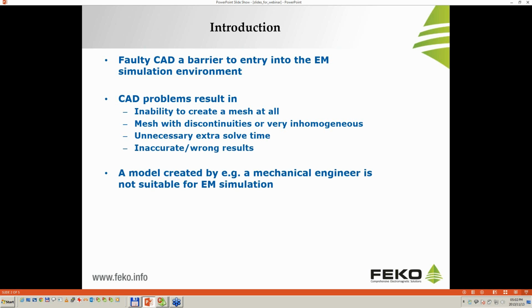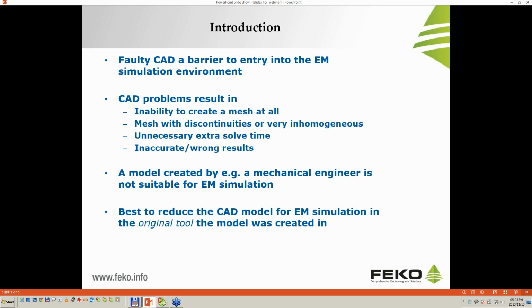Now, quite often a CAD model is created by a mechanical engineer and it is not suitable for EM simulation. For example, there will be much detail in the model. For example, there could be rivets and screws and many small details that we don't really need in EM simulation. Now, it's always best to reduce the CAD model for EM simulation in the original tool the model was created in. But that is not always possible, and many of our customers have requested that we add basic CAD fixing tools native to FEKO because they want to work in one tool.